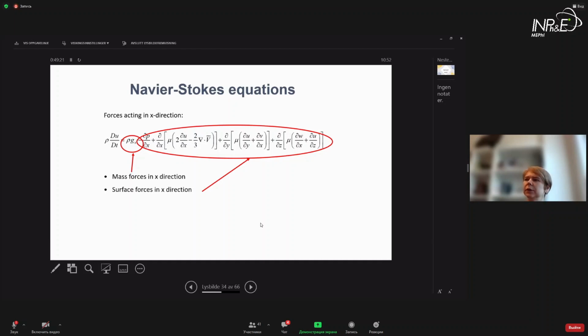Okay, if we neglect the viscous effects, we have an equation which is much more manageable. Of course, we can also restrain ourselves to 1 or 2 dimensions. And we can also simplify it a little bit by looking at the steady state equations, and we get more and more simple and manageable equations. Those of them you have probably done quite a lot of before. But what happens when we at last have to attack the full Navier-Stokes? What do we do then? When there is both a compressible and viscous fluid, and it's also non-steady, and we have to do something.